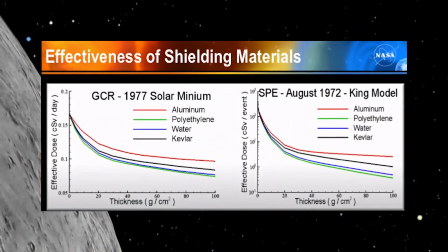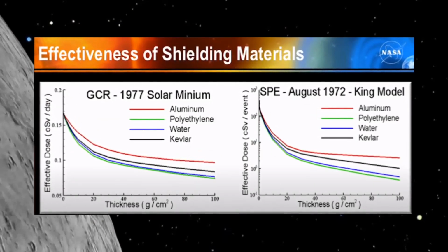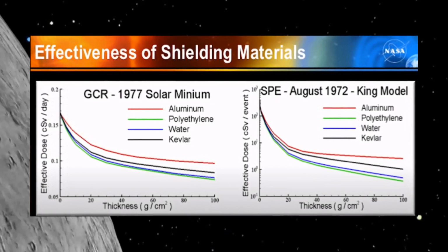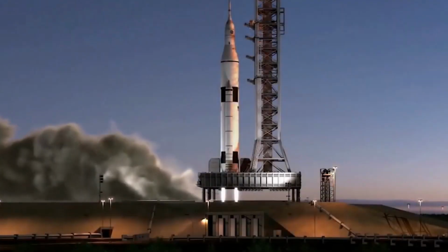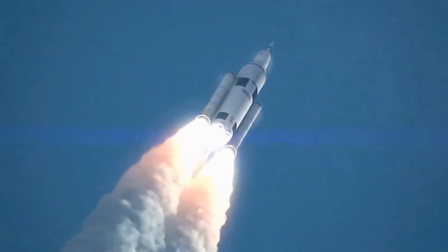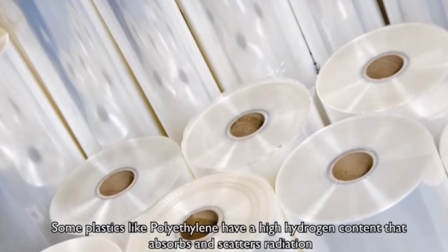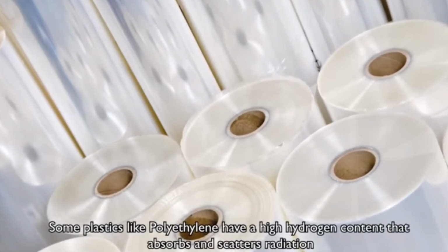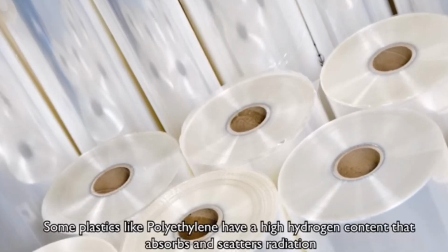To completely block radiation in the space environment, the spacecraft requires shielding of different materials, for example, lead or enormous amounts of water. Due to the excess weight of these materials, a launch would be a near impossibility with the technology available today. Therefore, spacecraft shielding is designed to decrease the intensity of radiation to acceptable limits for the astronauts using materials that minimize weight for launches.